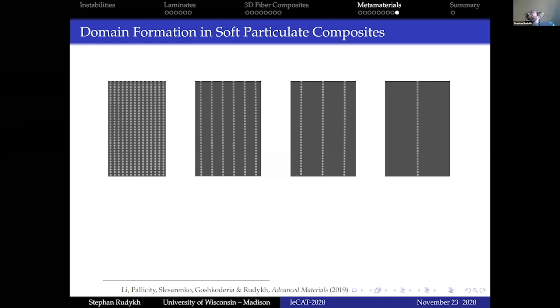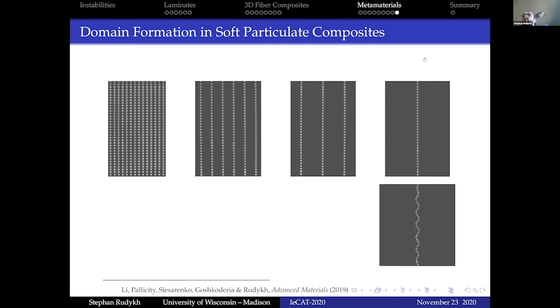So they're just finishing here. So just trying to explain, maybe give some initial thoughts about why this new instability formed here. If we start from this system of a single column of inclusions and then we compress it, we can expect something similar to a laminate to happen here, because we can think about this region as a collection. It's effectively a reinforced laminate, right? So we put the inclusion and put the stiffer layer here effectively. And so that's indeed what will happen.